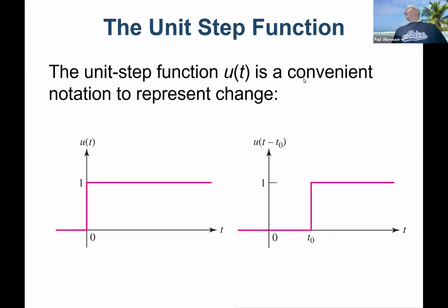Okay. So we're going through first order circuits, and we talked about how to analyze any first order circuit. Any first order circuit is a circuit that has an equivalent capacitor or an equivalent inductor. And obviously you can have a bunch of resistors, but we can't have two charge storage devices, capacitors or inductors, and treat it as a first order. That's a second order circuit or higher, could even be higher. And so we would have to do different circuit analysis techniques to do that.